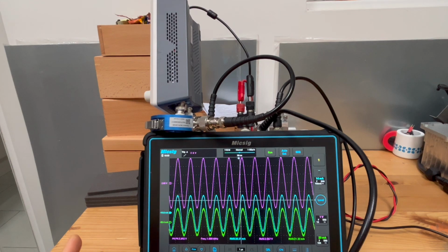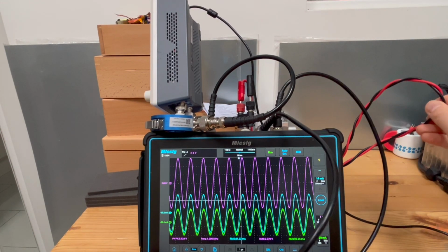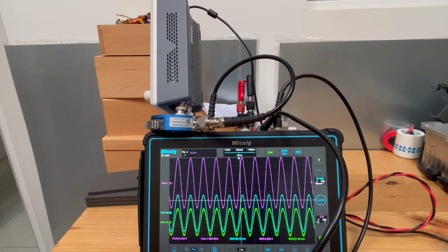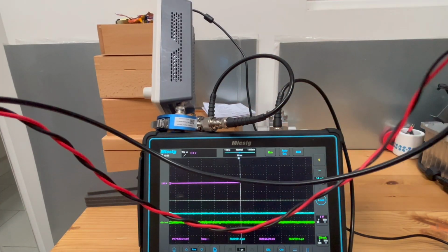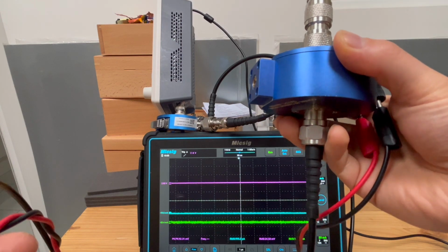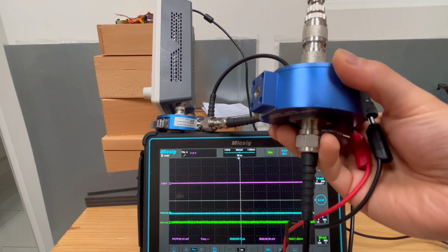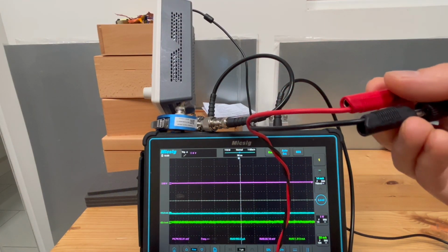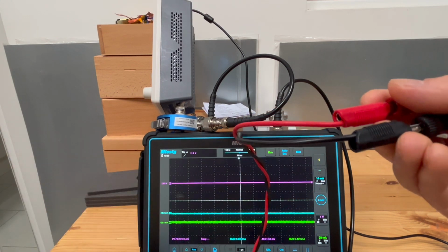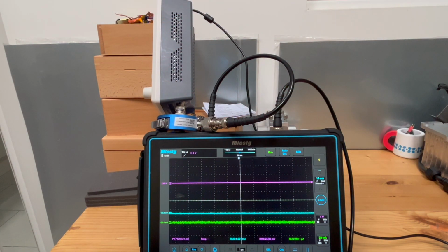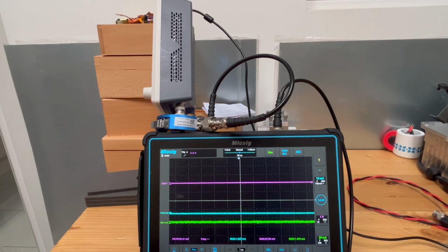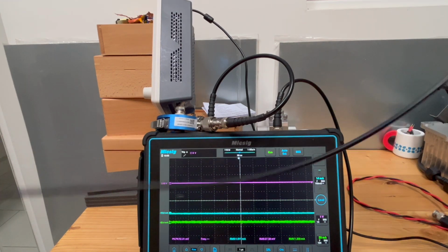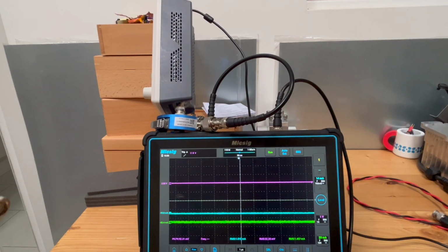So as I explained, now we are going to replace this twisted pair with a coaxial cable and see if there's any difference. But I wanted to introduce the current probe we use because in the previous case we used a twisted pair and I can simply clamp a current probe on the return path, which is the black wire, and monitor the current, okay? And this is about 1 meter long twisted pair. So in order to keep the comparison pretty much similar, I also got a coaxial cable of similar length, slightly shorter.